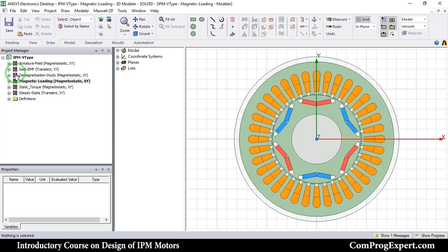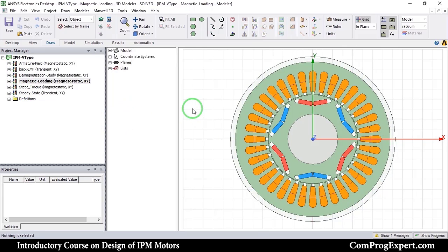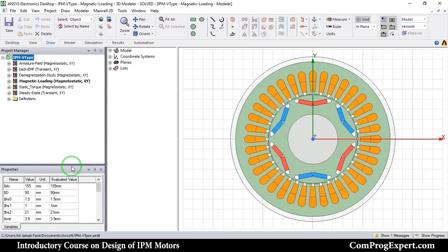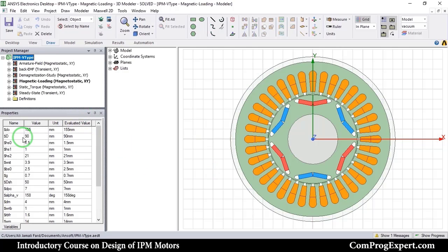Okay, and these are the files that we will generate from zero during this project. In this analysis that I explained, we need to do these steps. We need to create these designs for derivation of motor characteristics using the finite element method. First, we create the fully parametric design. These are design variables. Some of them are dimensions, and some of them are motor characteristics, such as the phase current, resistance of phase, number of turns per coil, and so on.